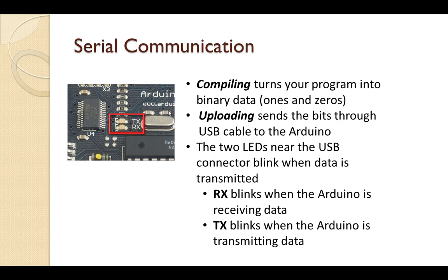One use is for compiling, and the second is uploading the code. While uploading the code, both the receiver and transmitter lights blink because it has to send. There is a bootloader with code to send an acknowledgement once the code has been uploaded.